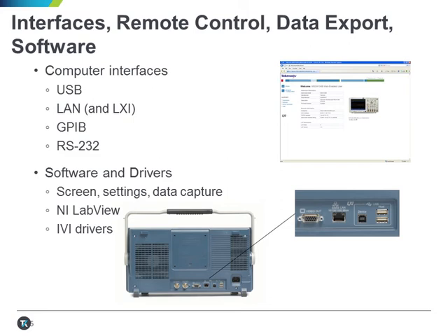Most manufacturers offer programs that you can use to grab screens, settings, or waveform data over one or more of the interfaces above. Tektronix calls our utility Open Choice Desktop. If you're a LabVIEW user, drivers are kept on the National Instruments website. You can usually just set up for the scope's model number, and this will bring up the drivers if they are available. IVI class drivers are also pretty common, but these are usually available from the scope manufacturer's website.